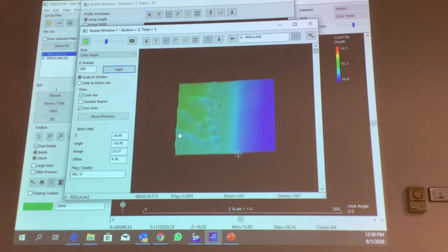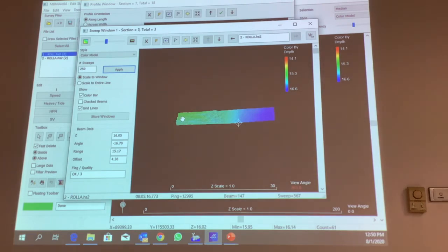So you see, you can move it up and down, and then you can also use this, and then you can edit out. Then you can just remove it. So it's different from single beam. Single beam, it interpolates, right? In multi beam, it'll just delete the whole point. So if you don't want that area, when you use it, it'll just delete everything.